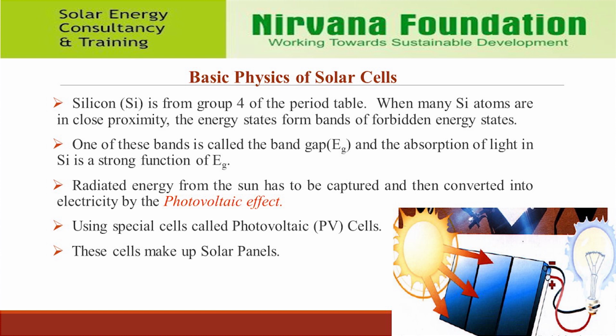A solar cell is made of two types of semiconductors, called P-type and N-type silicon. The P-type silicon is produced by adding atoms such as boron or gallium that have one less electron in their outer energy level than does silicon. Because boron has one less electron than is required to form the bonds with the surrounding silicon atoms, an electron vacancy or hole is created.